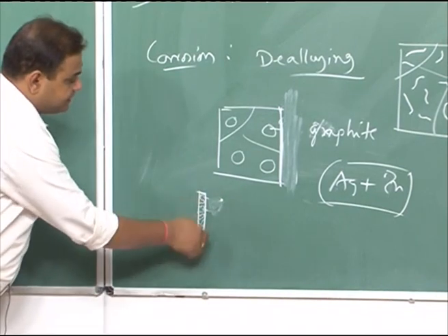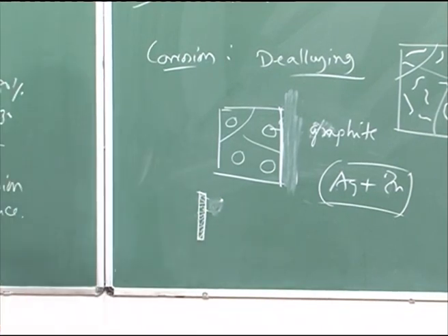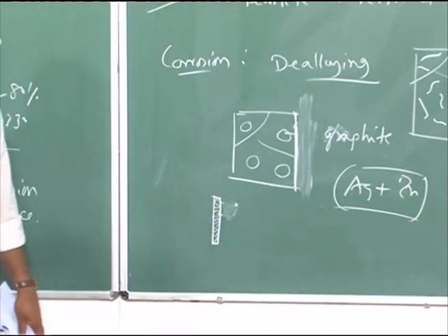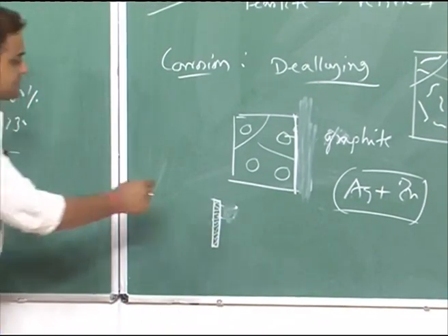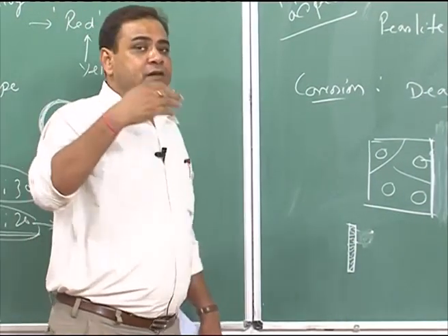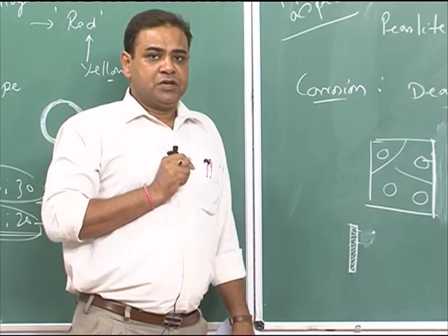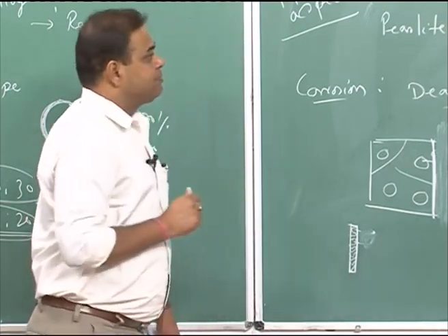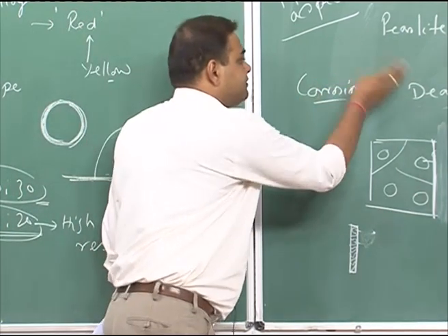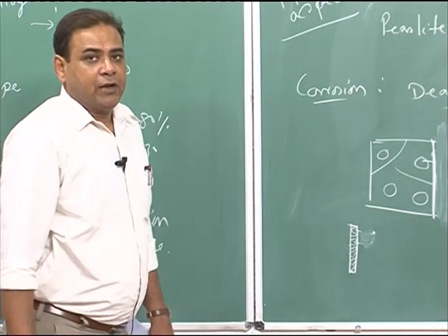So, it is basically made of silver then, and the silver network would form and create a porous material and porous template, and those pore dimensions will be in the range of nanometers. So, the nanoporous gold or silver template can be made by using this particular phenomenon called dealloying.